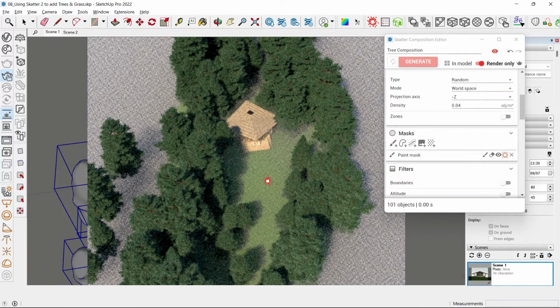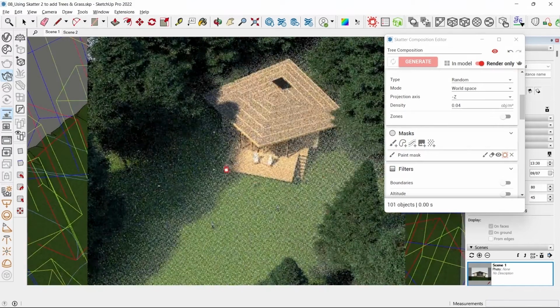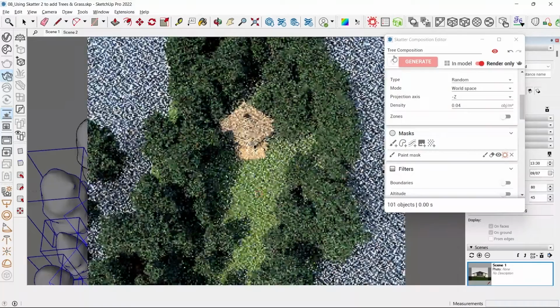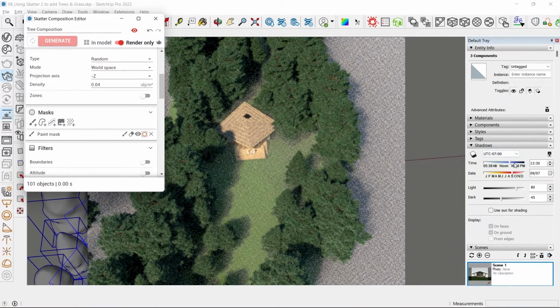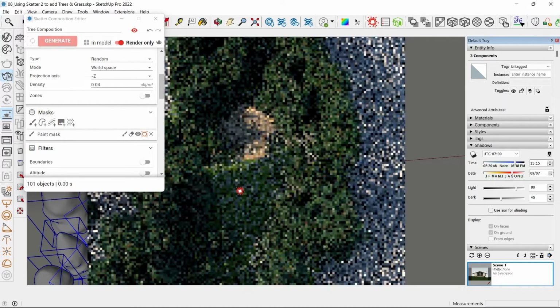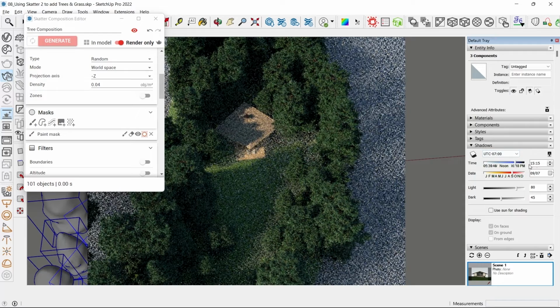No trees here, that's why you don't see shadows on the ground. Now if you want to see longer shadows, you can make the shadows longer. So that would work better. So we can do that as well. So I'm going to change the shadow settings. So let's go to shadows here and make it longer. So you will see the shadows update. You can see it becomes longer.